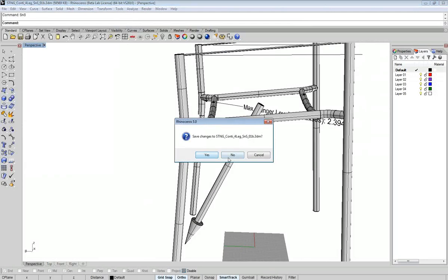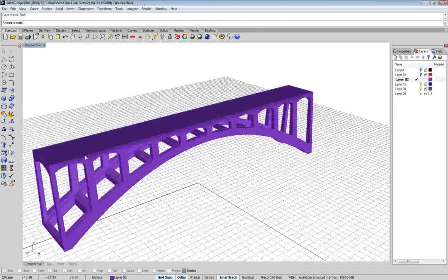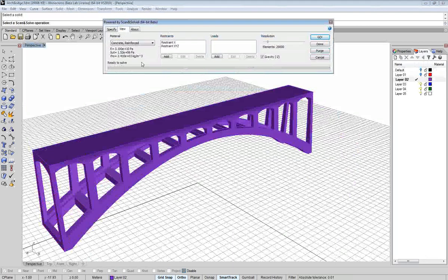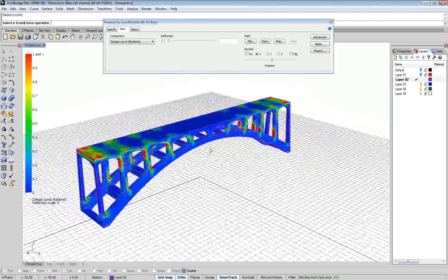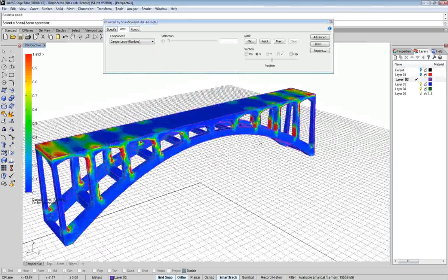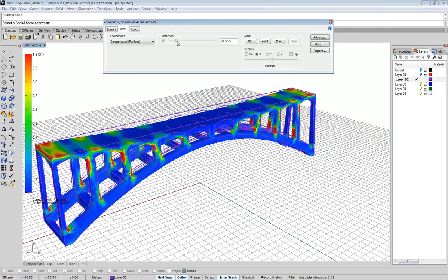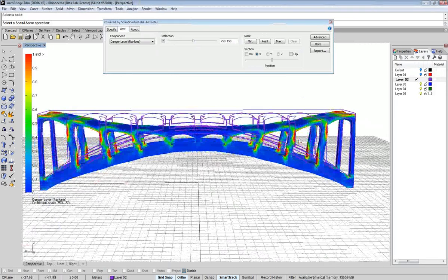Here's a civil engineering example. I just cooked this up the other day. In this case, this one is made of simulated reinforced concrete. Review the results, and it's obvious that I'm not a bridge designer because in this case, red is where my material is going to fail, which corresponds to locations where this bridge is in tension. And as I deflect it, you can actually see where those locations are. You can see where things are being stretched, as opposed to being compressed.